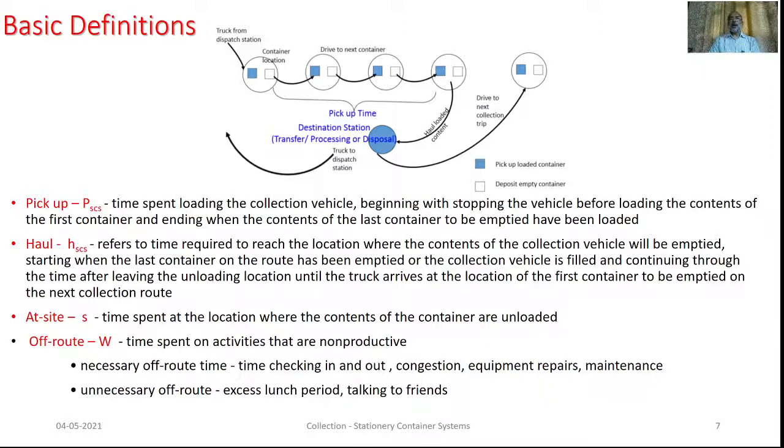Also, in addition, there could be traffic congestion, there could be unexpectedly arising repairs of the vehicle, there could be some unseen maintenance and associated time. So, in addition to pickup, haul, and at site, there will also be some allied time which is called off-road time.